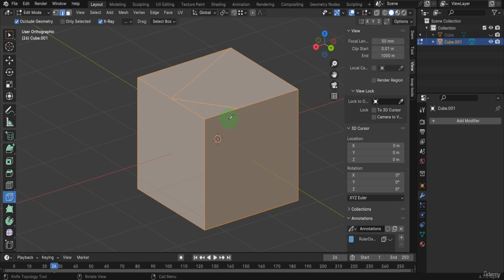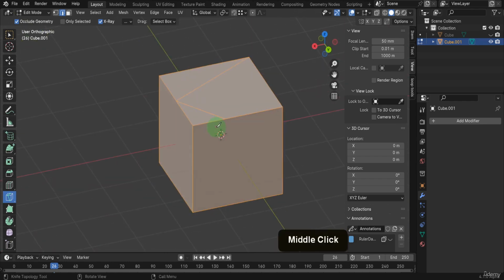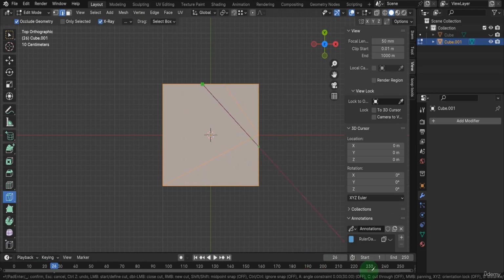Note that this method doesn't cut all the way through the mesh. To achieve a complete cut through the mesh, the cut through command can be used. For this, align the cut to the view by coming into a top view. Click an edge here for the first point. Notice that on the info bar below, the cut through setting is currently off. Press C to toggle it on.